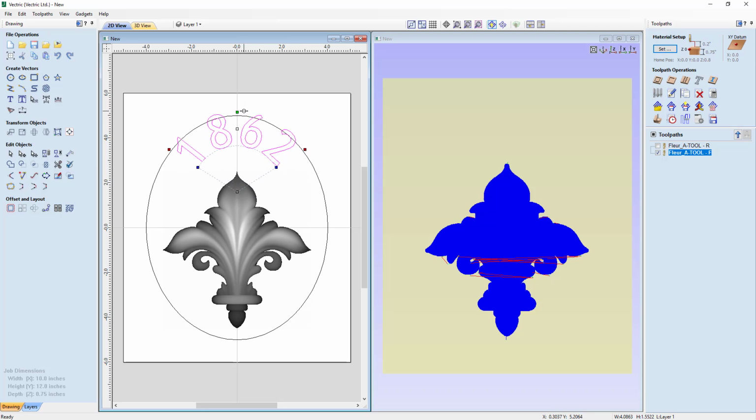I'm happy with that. Now I'm just not so happy with the spacing that's in between our letters. So using the same tool, if I left click between the numbers, they'll get closer together. If I hold down my shift key while I do that, I can make the space bigger. So in this case, I want to bring these a little bit tighter to the point where it looks pretty even.